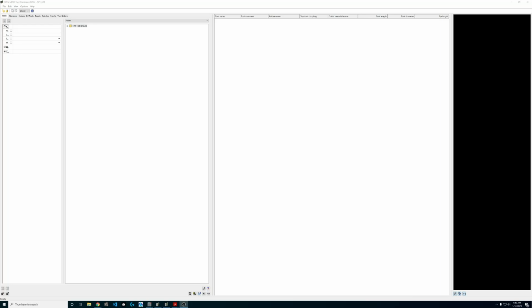So you'll see we're working inside of 2020.2. Now this is coming out January 12th. Sorry about that. And we have the 2021.1 release already. There's been some changes under the hood, nothing real significant. Namely, it's on the hyperMILL side. We've gotten support for some of the undercutting tools that we could always have defined inside of hyperMILL, but didn't actually have toolpath support for those tools outside of things like free tip geometry.